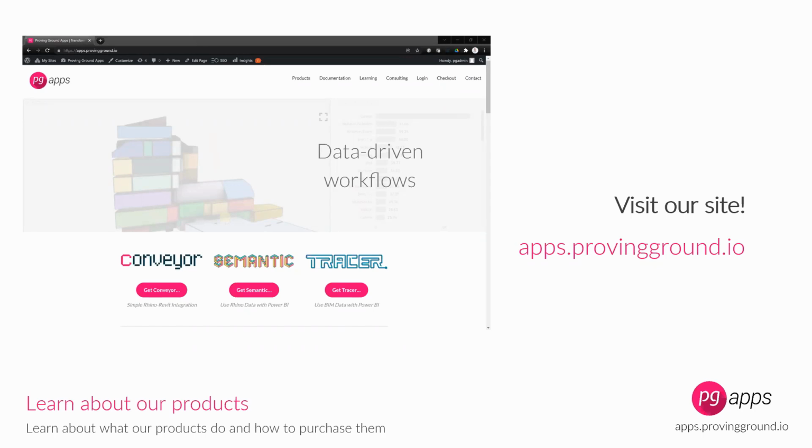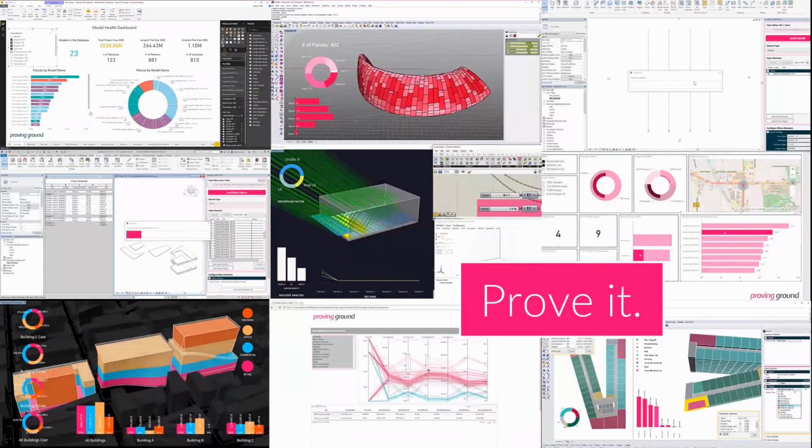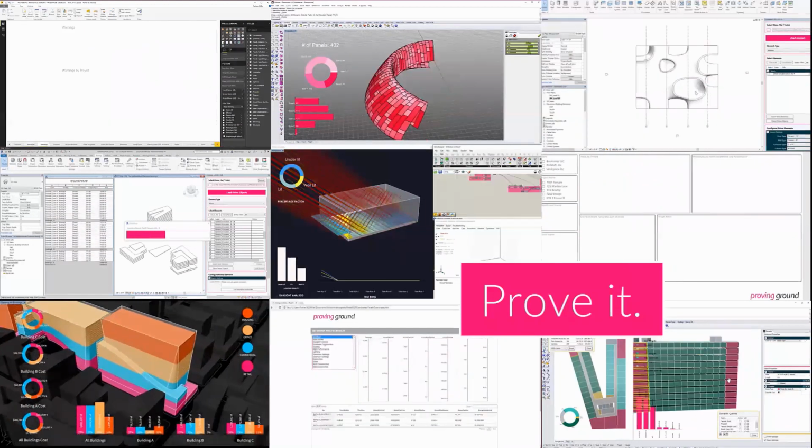So the idea is, okay, I'm going to open up, let's say, Revit 2022. Say I receive a model in Revit 2022 that's got a number of walls or floors or other objects in it, but I'm working in Revit 2020 for some reason. I need to get some of that data from 2022 back into Revit 2020. Well, the workflow there would be to open up 2022, select a number of different objects out of the 2022 environment, push those into Rhino, and then you can open up Conveyor inside of Revit 2020 and re-import those objects into Revit 2020.